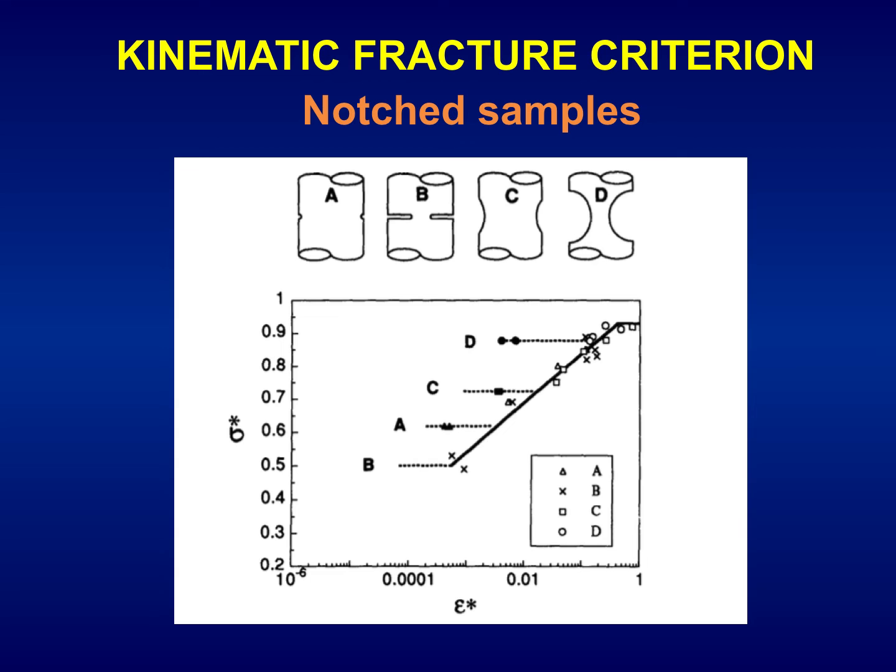Then, for the highest values of triaxiality, geometry B, we have the most deleterious, damaging or embrittling effect of hydrogen. The higher level of hydrogen embrittlement is obtained for geometry B in the quasi-static test with the maximum damage by hydrogen due to the higher triaxiality constraint level promoting hydrogen entry and diffusion by very elevated hydrostatic stress levels.